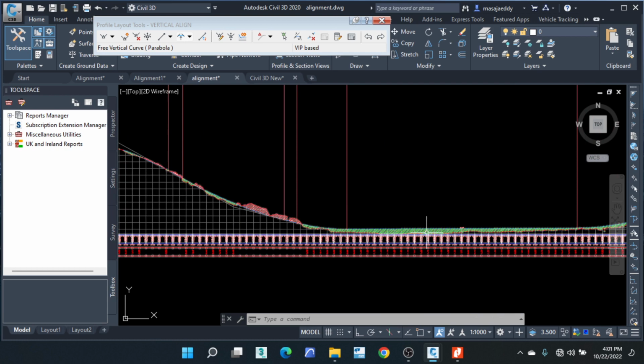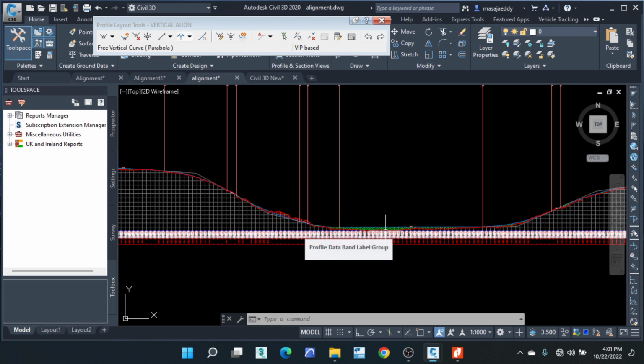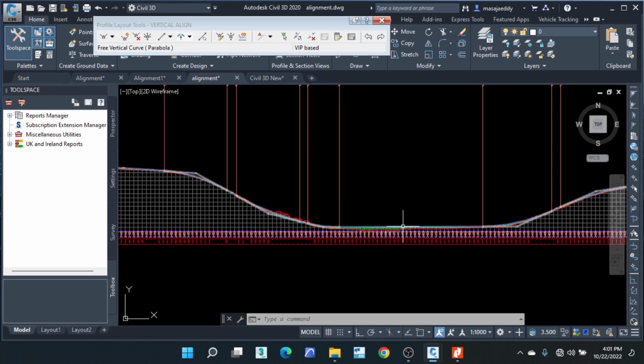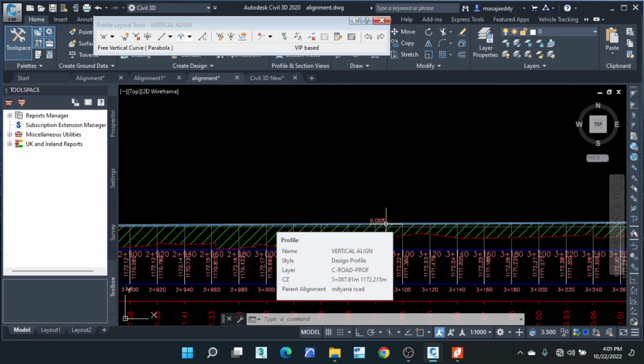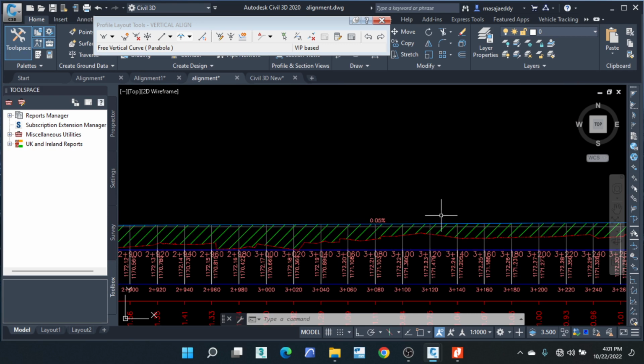So here in the swamp, we tried to adjust the profile to make sure it is about 0.5%, but it was creating high fill values. So we decided to have a slope which is less than 0.5%, but in this area we are going to bank the road towards one side so the water can flow off the road. I think it's clear here. So we do that throughout the entire road in the vertical profile, following all those parameters.